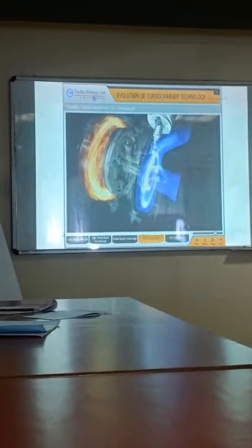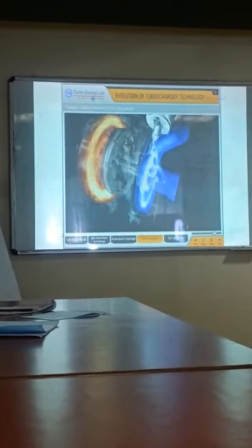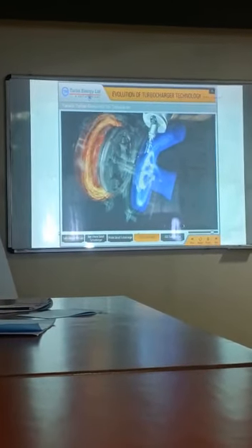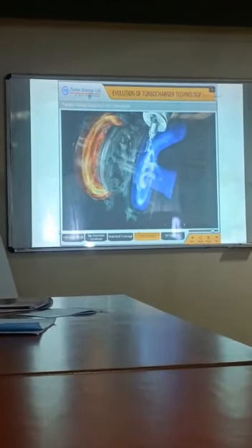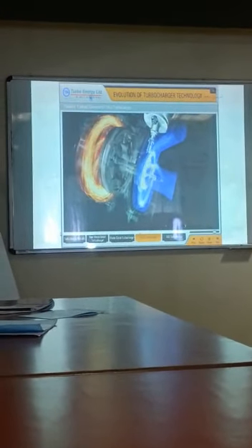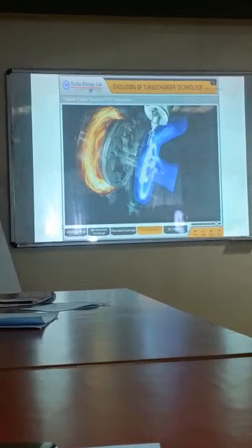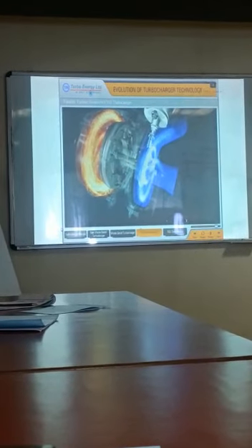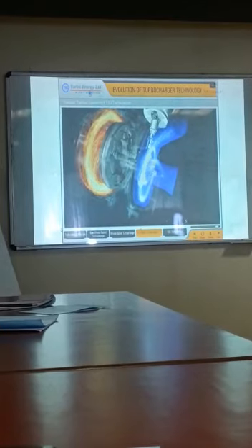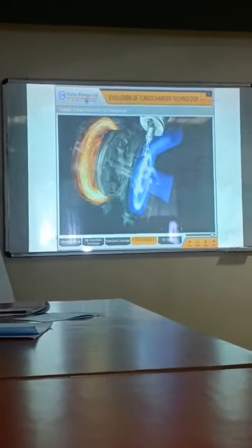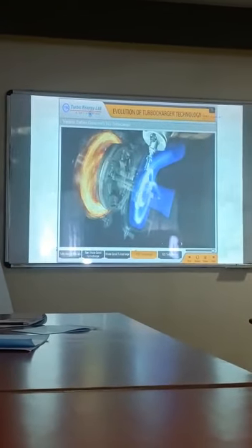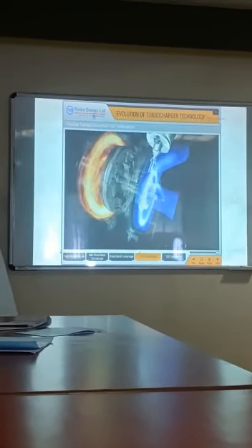Though the flow of exhaust gas and its temperature still determine the speed of the turbine wheel, based on the ECU demand, the actuator, with the help of vanes, closes or opens the exhaust gas passage in the turbine housing, leading to an increase or decrease of exhaust gas pressure inside the turbine housing, thereby manipulating the turbine wheel speed independent of engine exhaust gas flow.